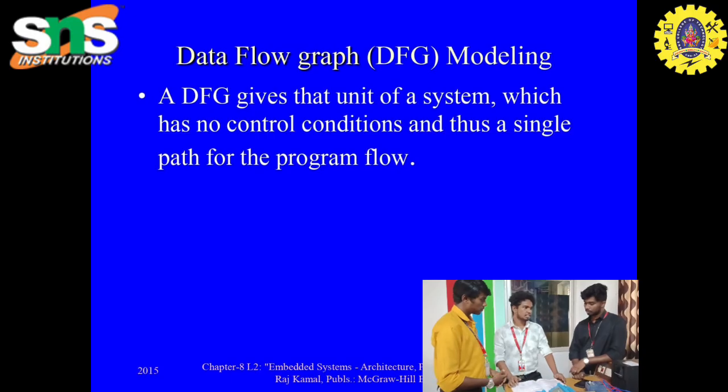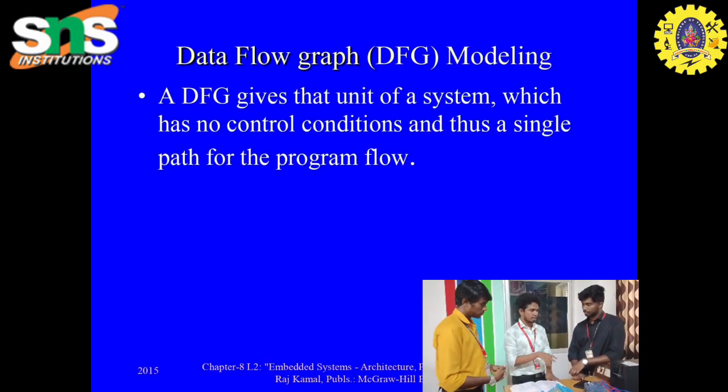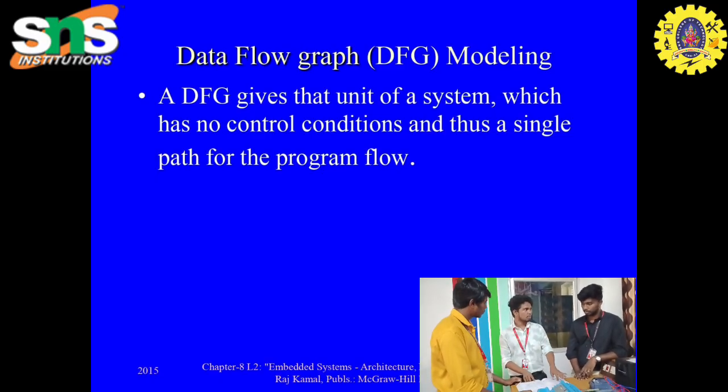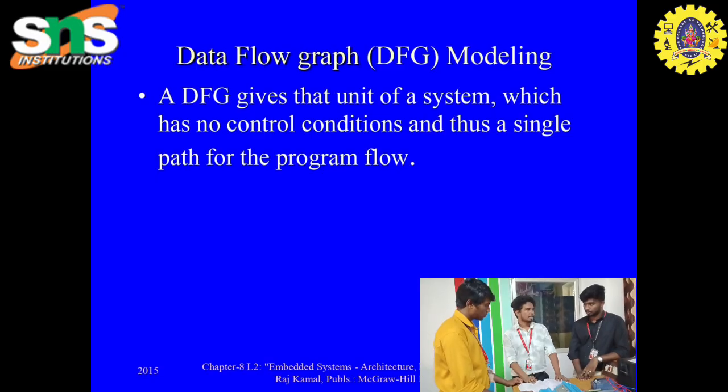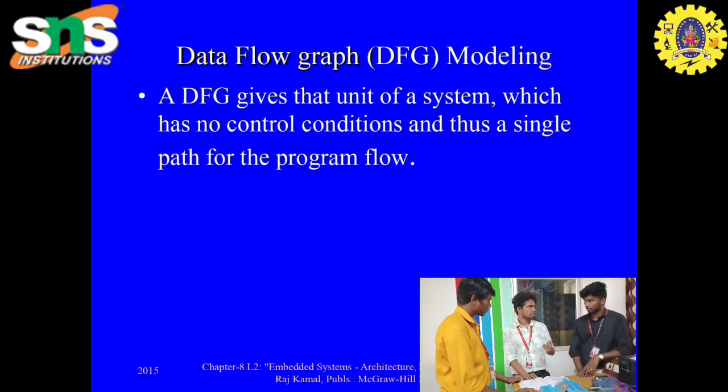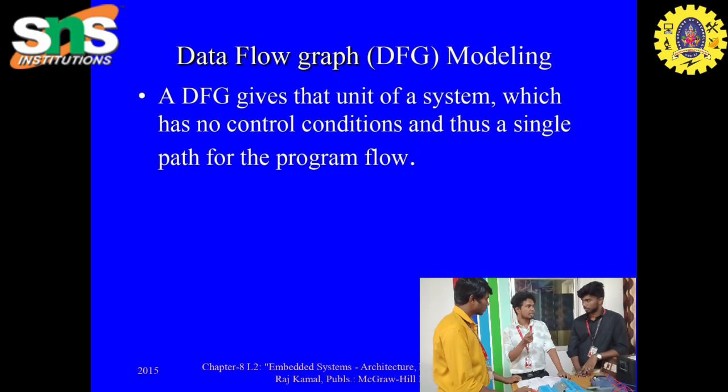What we will be discussing here is how, with this DFG model, the data flow graph model, we can see the data dependence of each process and each module. In this DFG model there are two elements: nodes and many edges. In the nodes we see the processing steps, in a digital camera or any other project we work on, and the data dependencies can be seen through the edges. That is the overview of the DFG model.